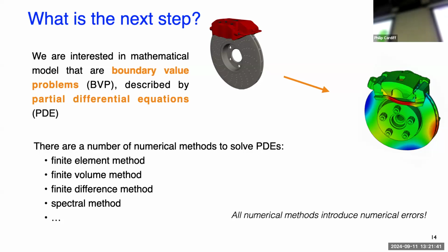There's a family, a continuum, of numerical methods that all have various relative methods. The reason we use these so-called approximate methods is that normally there's no analytical solution for boundary value problems that are in any way complex. If you have an infinite plate with a circular hole in it, then with a lot of complicated maths you can get an analytical solution under very restrictive simplifying assumptions. But if you change something, like the hole's no longer circular, or we have a loss of plastic material, it's essentially impossible to derive an analytical solution. So that's why we use numerical methods.